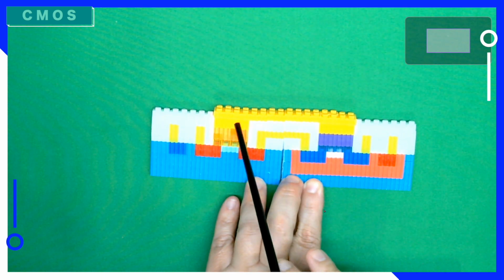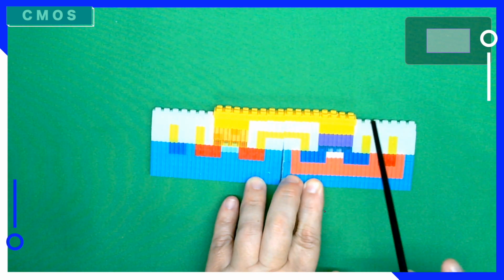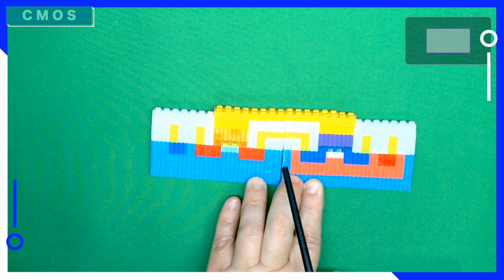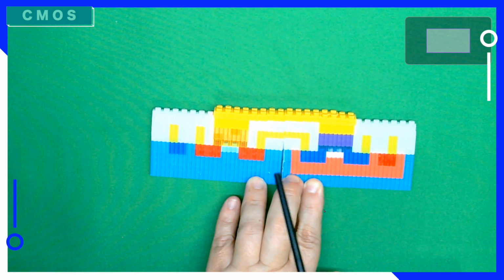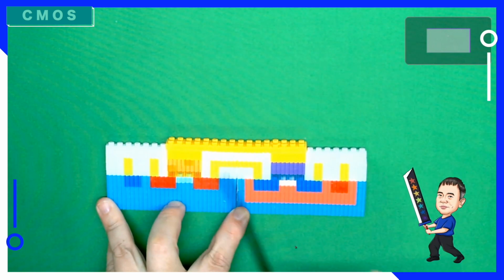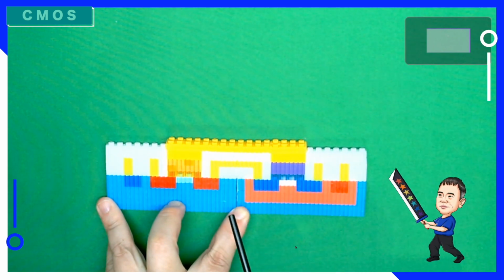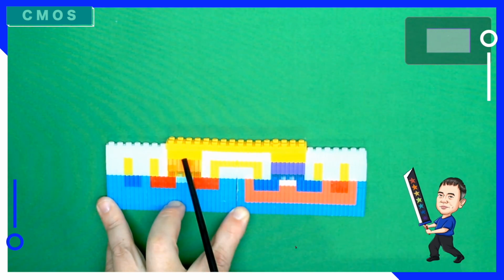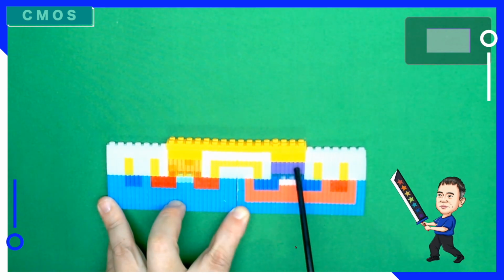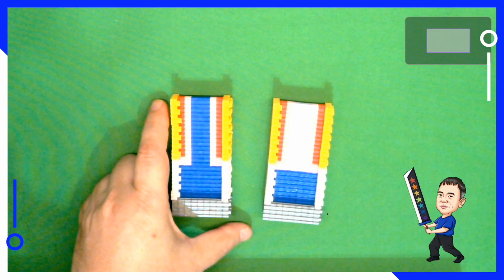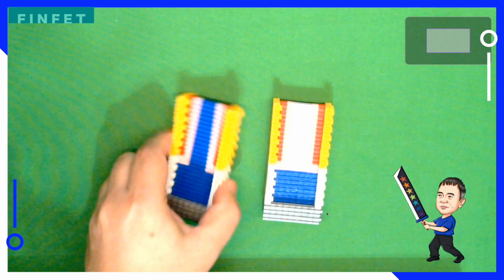If you apply a positive voltage, here opens. If negative voltage, here will open. So complementary means only one will open and the signal will come out. The signal will come out from one of the inputs and go to the output here, but only one side will come out. One and only one side. Apply positive voltage here, apply negative voltage here. That's the word complementary.